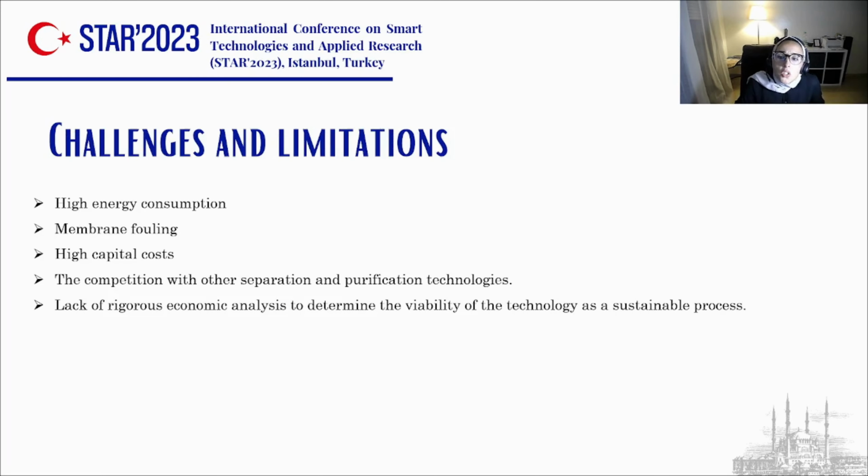ED technology faces a lot of drawbacks, such as high energy consumption, which is considered the number one trade-off of ED technology. Then membrane fouling, which reduces the efficiency of the process, the high capital cost, the competition with other separation and purification technologies such as distillation and adsorption, and the lack of rigorous economic analysis to determine the viability of the technology as a sustainable process.